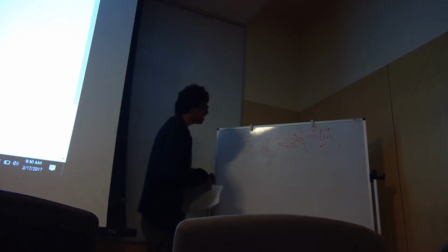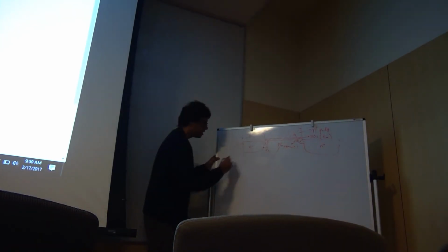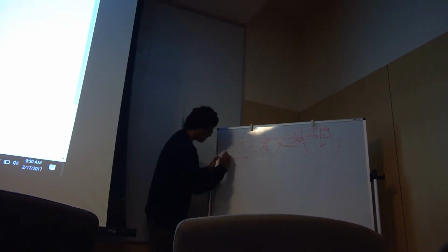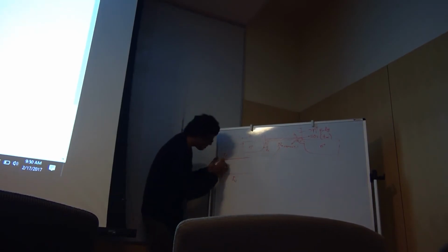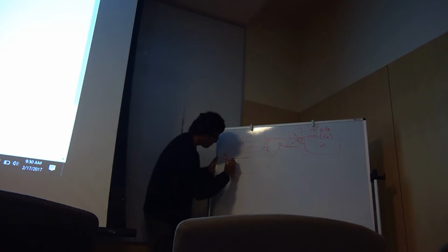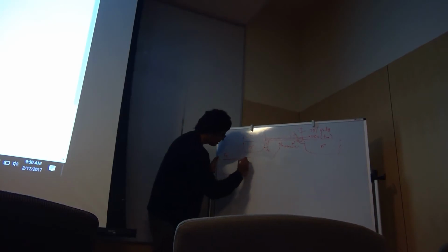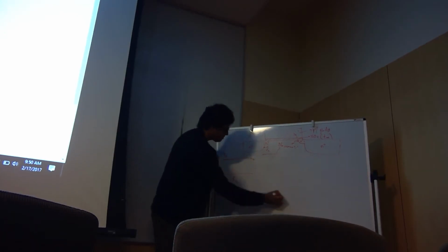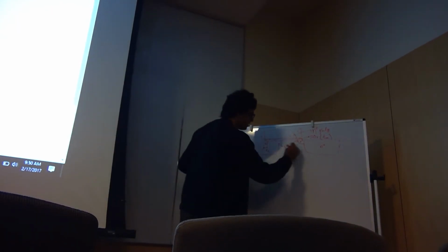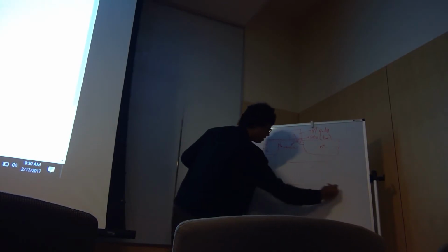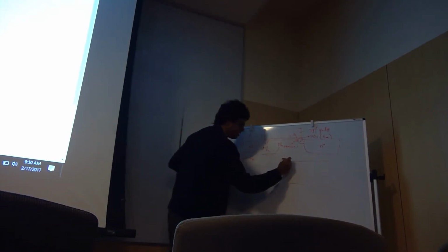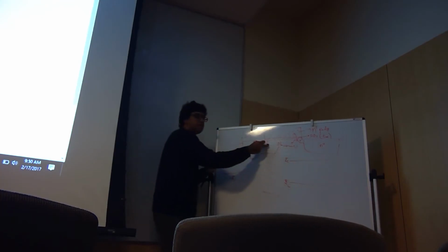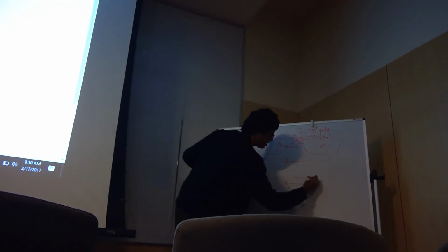Okay, I'll go over this very quickly. So in the polysilicon, you have a conduction band, valence band, and because this is heavily doped, your Fermi level is very close to the conduction band. So the Fermi level will be somewhere here. The oxide is an insulator. It has a huge band gap. It has its own conduction and valence band. And then your silicon has its own conduction and valence band, and it's p doped. So your Fermi level will lie somewhere here.